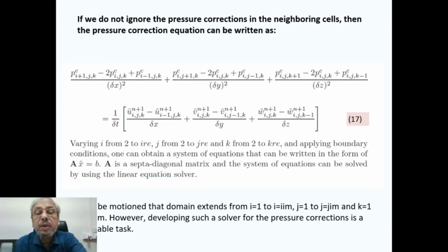What we can say is that basically one can solve the pressure correction equation this way by setting up a matrix and having the pressure correction terms solved directly from the matrix. But as you know, setting up such a matrix equation and the solution techniques are both very much involved.